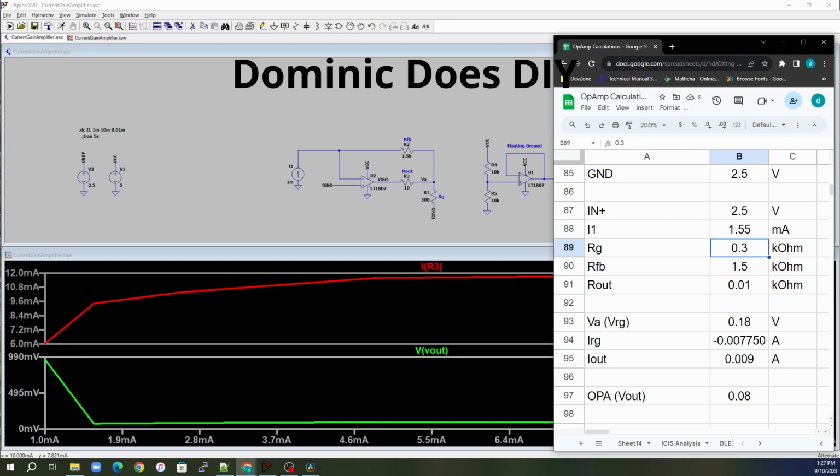Well, remember how the formulas are written. Your V out is based on your VA minus the voltage drop across your output resistor. So how can we reduce that voltage drop on the output resistor? Just make it smaller. One of the easiest things we can do right off the bat is, instead of using a 10 ohm resistor right here, we take this down to a 10 milliohm resistor.